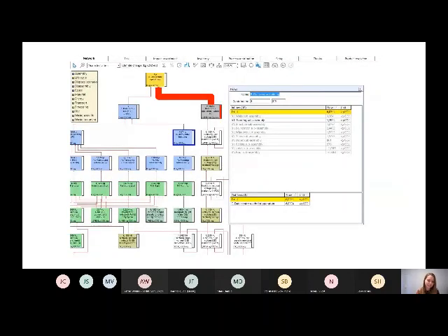And then we go on to the other side, and we touch the data center building. And what we notice here is that the main sources come from the walls, flooring, structure, and foundation. And if you go one step further, you discover that in terms of walls and foundation, the environmentally polluting flow would be concrete. When it comes to flooring, we're talking about glued laminated timber. And when we're talking about structure, the impact comes from steel.